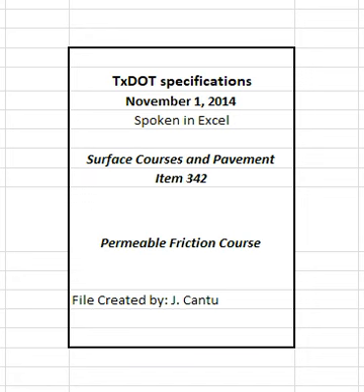Suspend operations and take immediate corrective action to eliminate severe thermal segregation unless otherwise directed. Resume operations when the engineer determines that subsequent production will meet the requirements of this section. 4.7.3.2 Windrow Operations. Operate windrow pickup equipment so that when hot mix is placed in windrows, substantially all the mixture deposited on the roadbed is picked up and loaded into the paver.